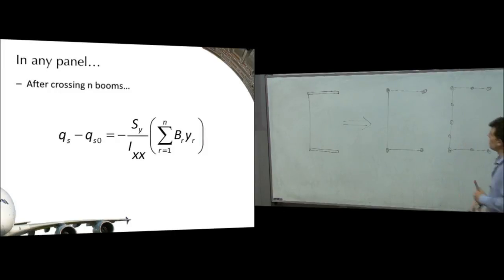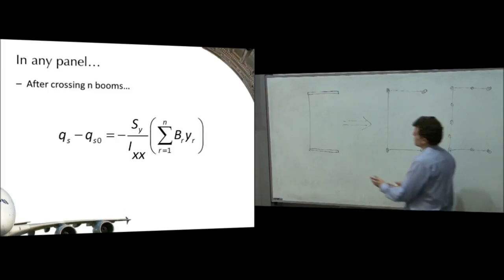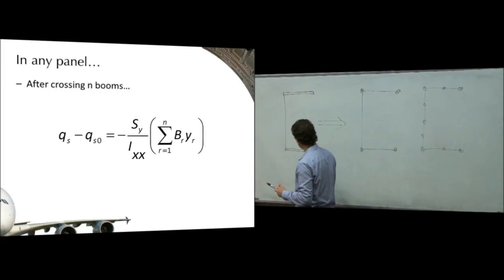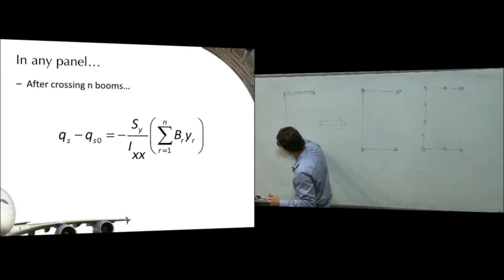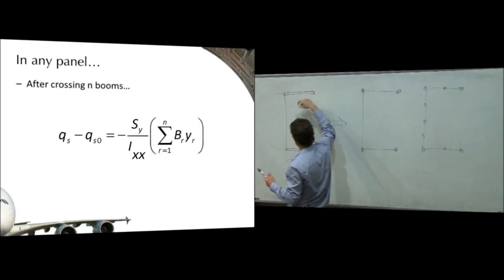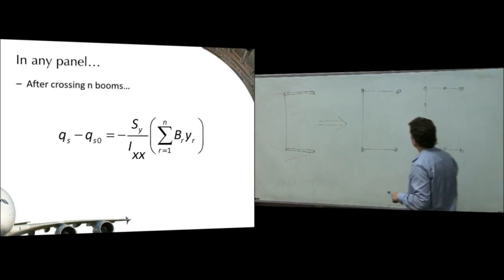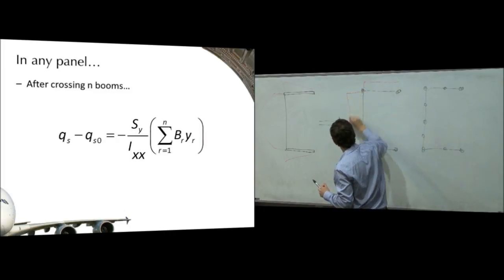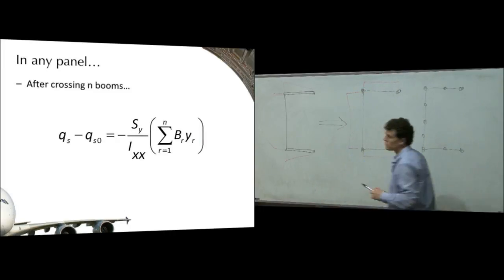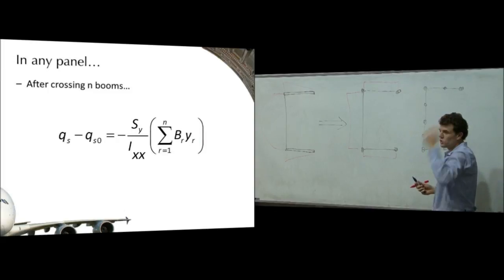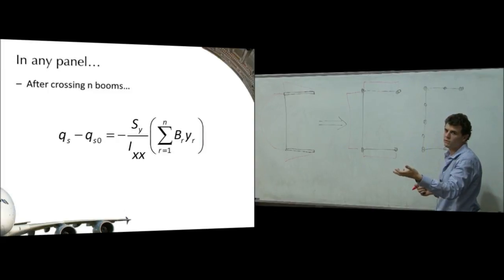Okay. And obviously this is a continuum problem. We've got lots of integrations here. Things are going to change linearly, and then they're going to be parabolic. Here our shear flows are constant. Okay, there's no variation in this. So the more points we put in, the more resolution we've got of the things that we're actually trying to find.